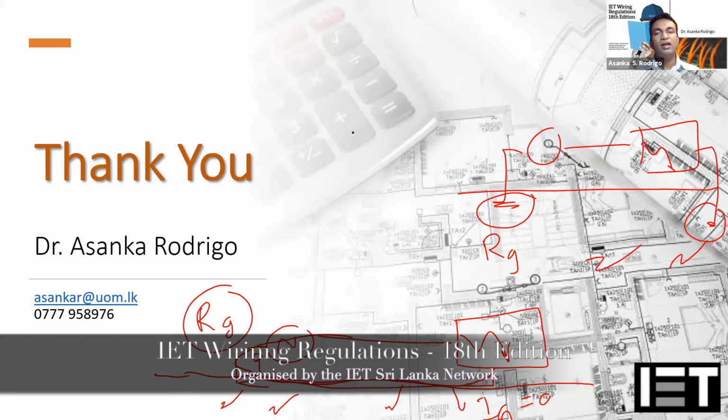It's not just blindly putting in whatever RCD is available from the market. At the least you need a type S RCD, because you have another RCD inside the building, inside your home, so this RCD should be at least type S or a delay-type EFR.